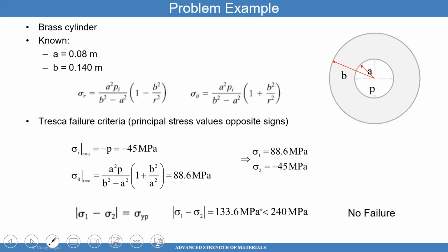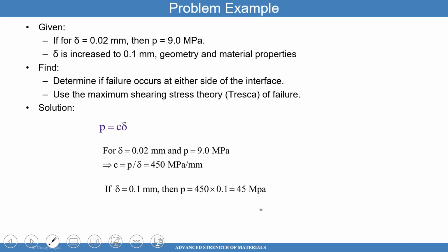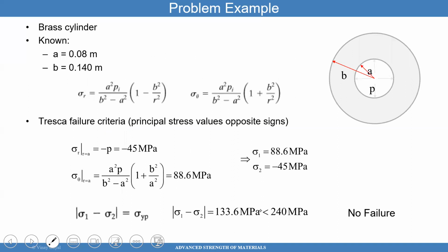So what I'll do then is study the problem a little bit more. Now we know the interface pressure to be 45. I'll first look at the brass. So the pressure here in this boundary is 45, according to the problem statement. I can use the equations for a cylinder under external and internal pressure applied. It turns out that there's only internal pressure applied here of 45. I can plug in all these numbers because I have the radii for the different geometric factors.